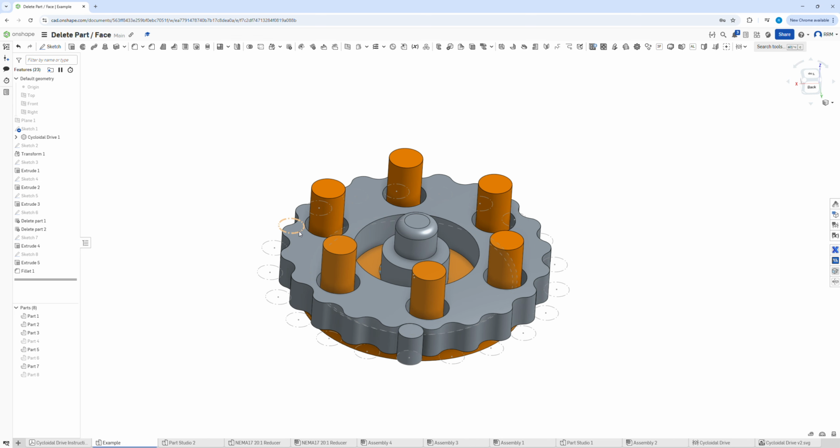Now this is an example of a cycloidal drive. Have a little Google of it. They are fantastic for reducing speed. They have an offset eccentric shaft in the middle and two of these waveform-like teeth that will move around to rotate something, usually driven by a stepper motor or something similar.